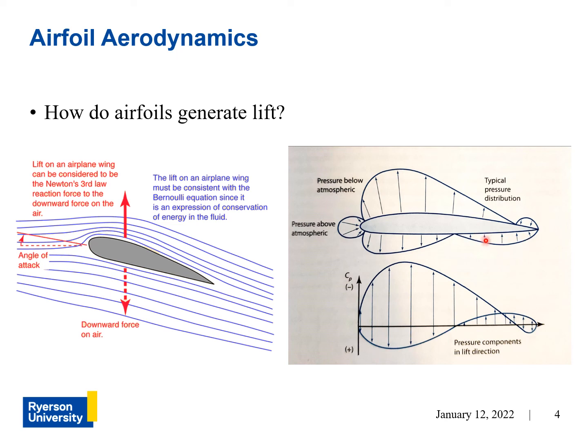So that's why, as with here, the region has above ambient pressure. Now, if you were to take all these vectors, you can see that most of the lift is produced by the upper surface. And you can also see that there's a net pitching moment causing the airfoil to pitch downwards because of the way the airflow is flowing along the surfaces of the airfoil.